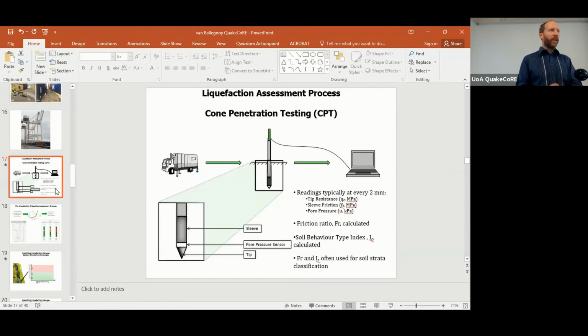When we compare those pre-earthquake CPTs with post-earthquake CPTs, we see that there is very little difference in the CPT tip resistance and the sleeve frictions. So while there appears to be, the ground might have increased in density just slightly, but it hardly registers as a change.